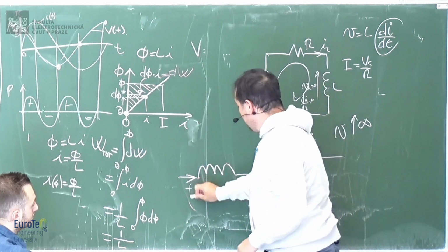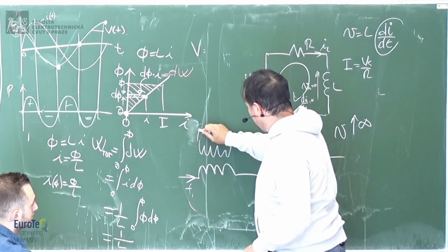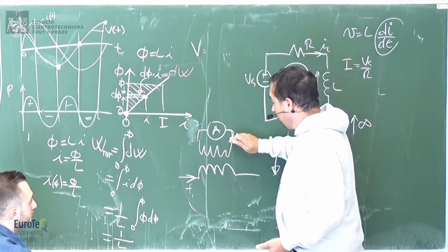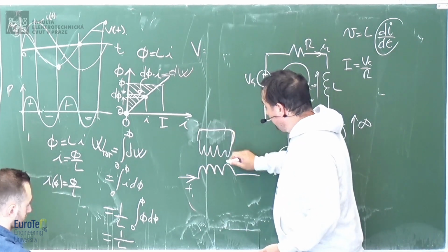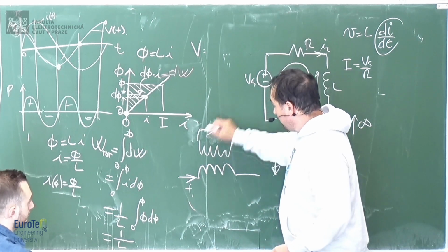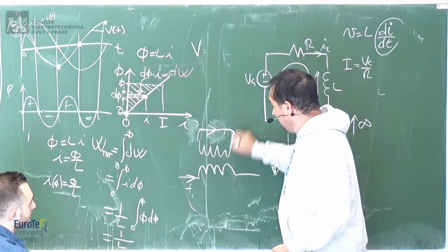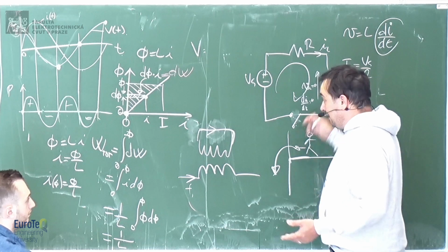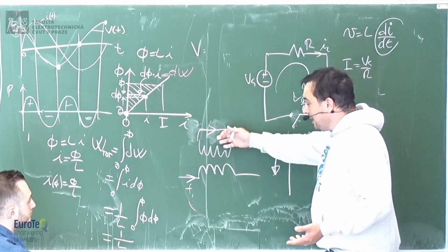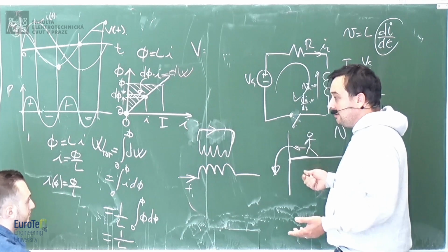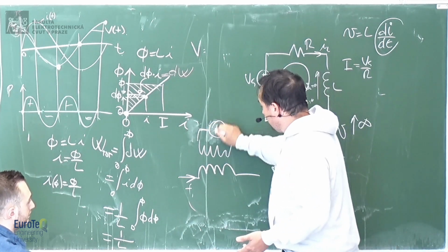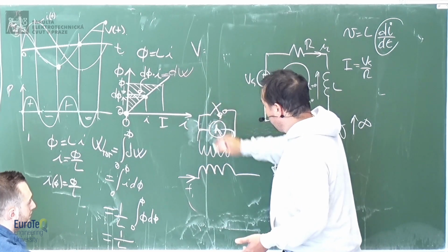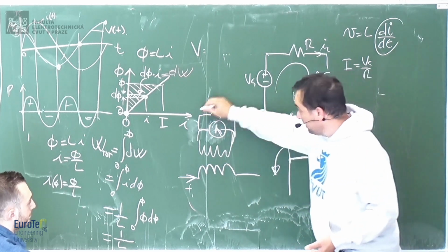circuit where you want to measure the current. You have here your ammeter. Now the ammeter is a short circuit, okay? So you can ideally see it as a short circuit. So there is some current here which circulates. And you cannot just think that you can stop a current, an inductive current basically, by opening, because otherwise, boom, spark. So that's why you always have an ammeter, but always available a shunt here that you should close before removing an ammeter so that the current will circulate.